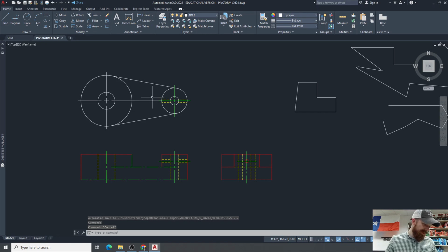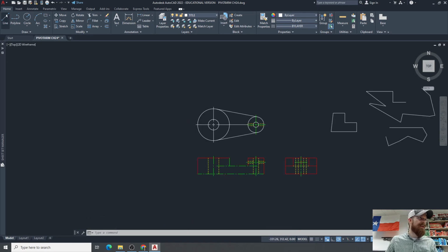There's also a tool called blend. This is important. Let's talk about this one. I know I'm probably going over on my time. I apologize. So the blend tool, what does the blend tool do? This command blends the gap between two selected lines or curves by adding a spline. So let's go blend, first object, second object. Do you see how that would be handy?